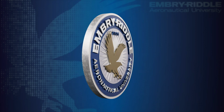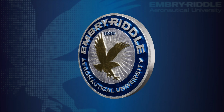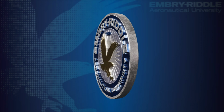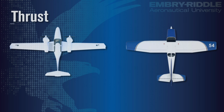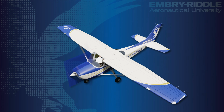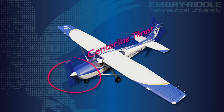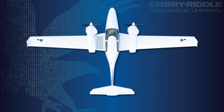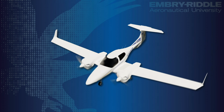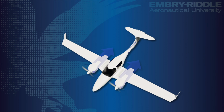Now that we have reviewed the four forces acting on an airplane, let's look at how they differ on multi-engine and single-engine airplanes. Thrust. On single-engine airplanes, thrust acts right down the longitudinal axis of the airplane due to the position of the engine. This is also known as centerline thrust. On the other hand, the thrust on most multi-engines does not act down the longitudinal axis due to the engines being mounted on the wings.